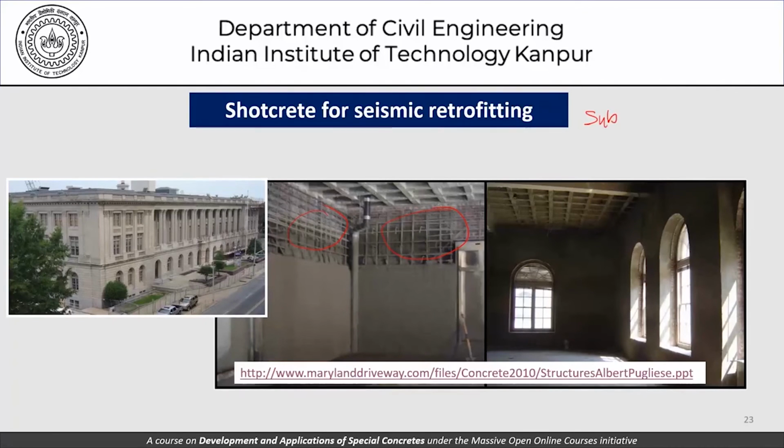So one advantage of using shotcrete in the repair works especially is that it works with any of the substrate materials. We have seen examples where we had a steel pipe. We saw an example where it was a brick sewer lining. We have normal reinforced concrete kind of bridge structures, and we have a building kind of structure where these panels could be made of either brickwork or any other material that is locally available and has been used.